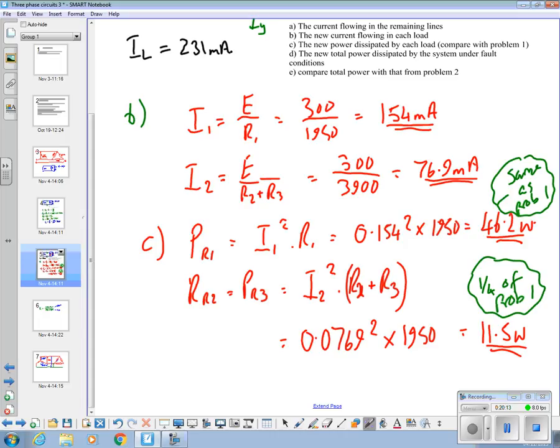Yep. That's why it's a good idea to up the voltage on the national grid, because then you bring the current down, and every time you halve the current, you quarter the power losses in the cables and all sorts of things. What if you do that to a motor? Momentum might keep it going, but they certainly will vibrate, and they won't last very long.